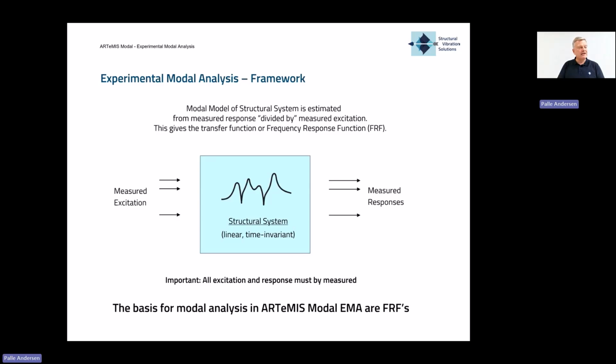If it heats up, you get another stiffness than if it's cooled down. And that means that when you have another stiffness, you also get another natural frequency and so on. So it's really important that the conditions are the same throughout the test you're doing. Otherwise, things will be messed up inside the analysis and you will get some kind of average of what's going on in this case here. So make sure that you are in an environment where you get the conditions to be the same throughout the whole test.